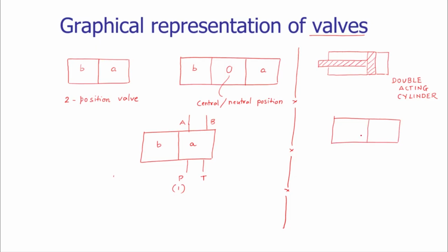Now the normal position we are considering here is the contraction or the retraction of the cylinder. For the retraction, as I mentioned, we have to have the pressurized fluid at the rod side. So let us connect this to the rod side.